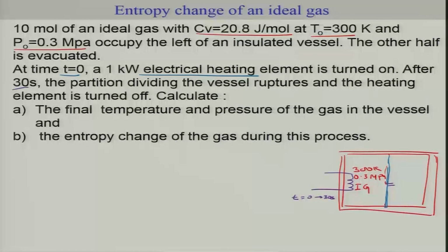One of the things which we can do is we can first apply the first law of thermodynamics over this system here. So, delta U is going to be Q plus W, and since there is no specific heat as such, it is basically electrical heating, and essentially this is electrical work which is applied on the system. So, essentially we are going to put Q as 0, because this corresponds to the electrical heating element, and now delta U I can write as N CV delta T.